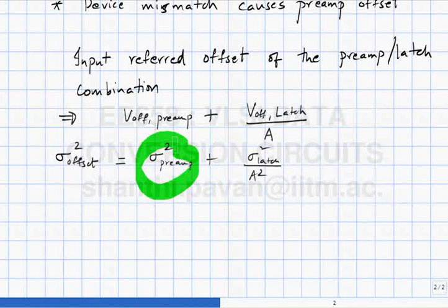While it is true that putting an amplifier up front before this whole combination definitely reduces the contribution of the preamp at the input of the combination, the input offset of that amplifier that you put in before will dominate the whole picture, and you're again back to square one, right? So going on putting gain without doing anything, because fundamentally offset is coming from device mismatch, and in all these solutions we are not addressing the fundamental problem of mismatch at all.